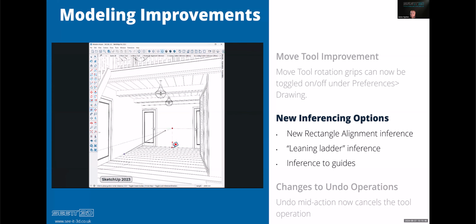So here we have the guideline drawn at the back, and I'm trying to infer another guideline. I've managed to lock it because I inferred to the midpoint on the floor, and then I've drawn a line from the intersection point where the two guidelines meet. 1 meter. I'm just doing that as a proof of the height. So I'm taking the pencil now and I'm clicking on the ground to draw a vertical line coming up.